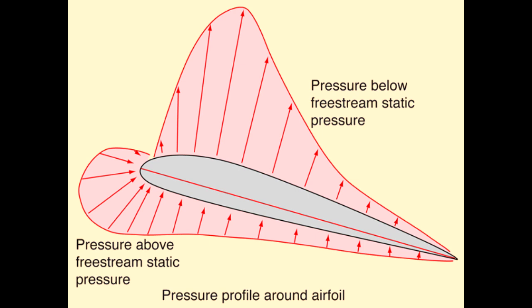Of course, we also have the shear stress due to the air viscosity, but for this type of flow, the pressure force is much greater than the shear stress, and the shear stress, due to the fluid viscosity, the air viscosity, will primarily induce drag on the airfoil.